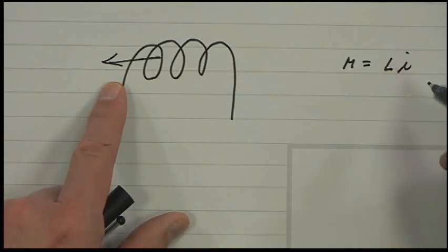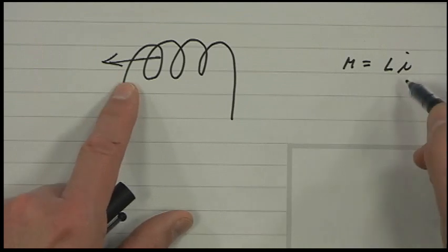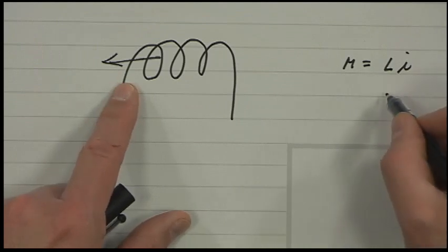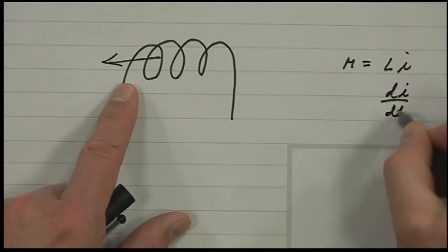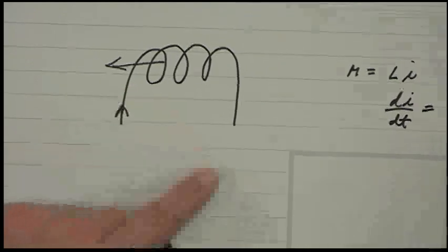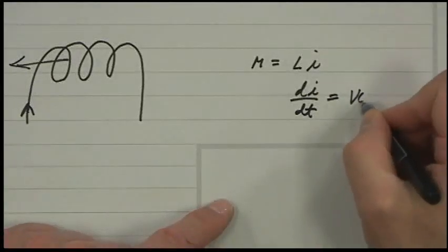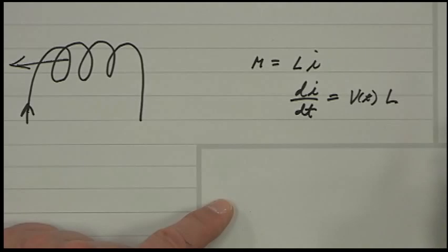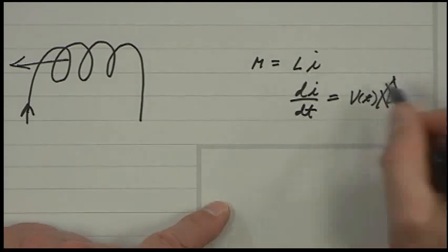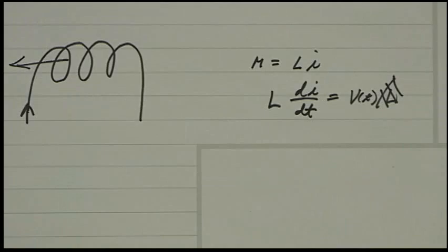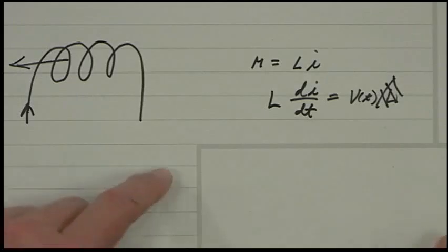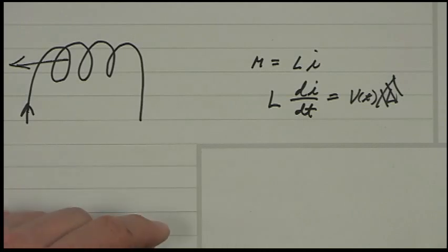One thing to remember also is that if this is an inductor, then if you recall, the derivative of the current with time is equal to the voltage divided by the inductance. The other way of putting it is: dI/dt times L is V of t. Anybody who's ever unplugged a vacuum cleaner knows about this, because the vacuum cleaner is highly inductive.